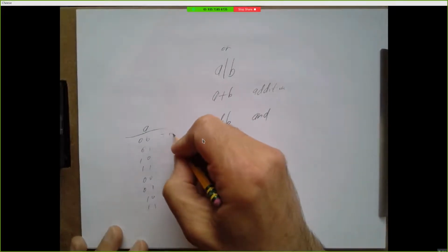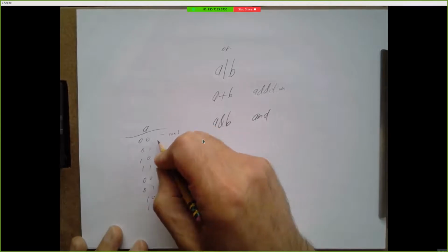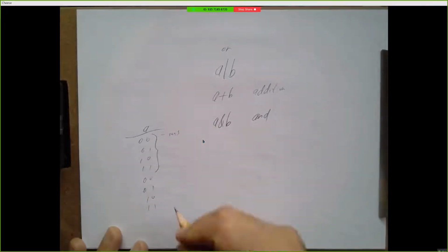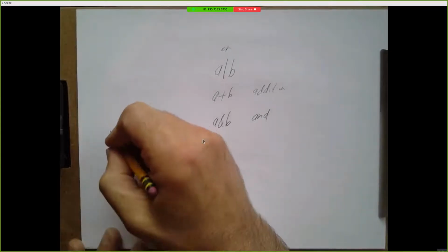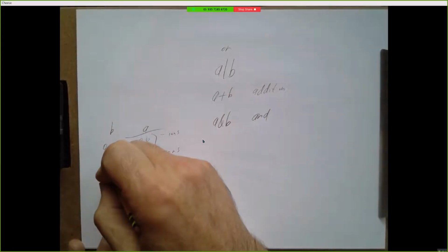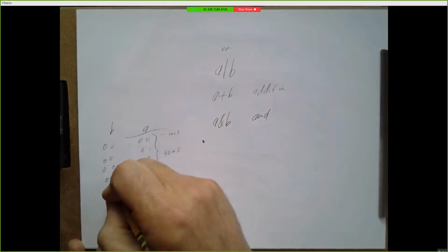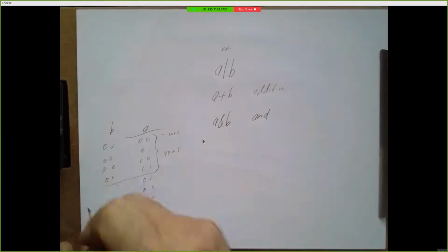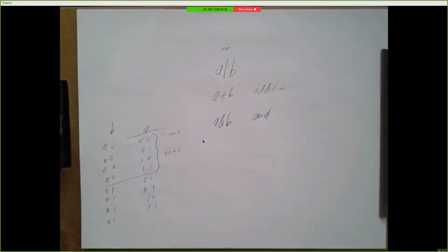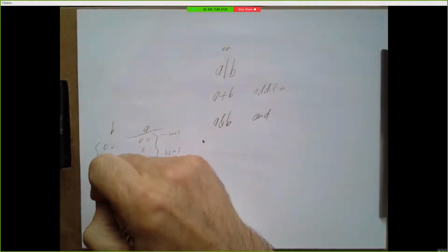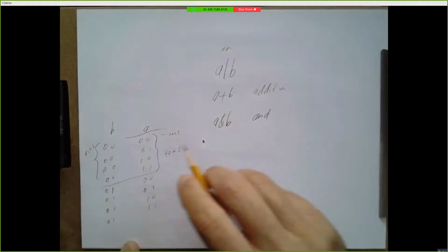And I'm saying that each of these is going to be 10 nanoseconds, which means to go through all 4 values is going to take 40 nanoseconds. So I'm going to make another input B, and I'm going to count slower. Every 40 nanoseconds, I'm going to increment B. Right, so I'm going to say B is a 40 nanosecond clock.